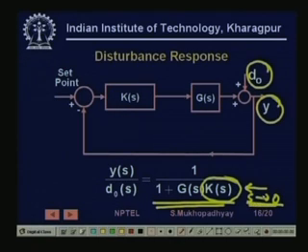The same reason why E goes to 0 with integral control, even the effect of step disturbances will also go away, because the integral value will rise and provide the additional torque to actually take care of the disturbance.